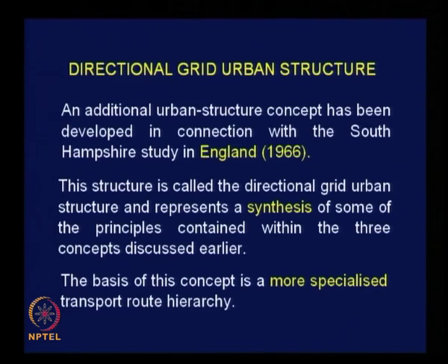These people wondered, why not create roads in each category with emphasis both on speed as well as land access. They thought of type 1 category roads. Within type 1, 2 types: one with emphasis on speed goes with high volume, the other one with the emphasis on land access, again with high volume. So, they ended up with 8 different types of roads. Type 1 through route, type 1 access route. Type 1 through means emphasis on speed, type 1 access route means emphasis on land access.